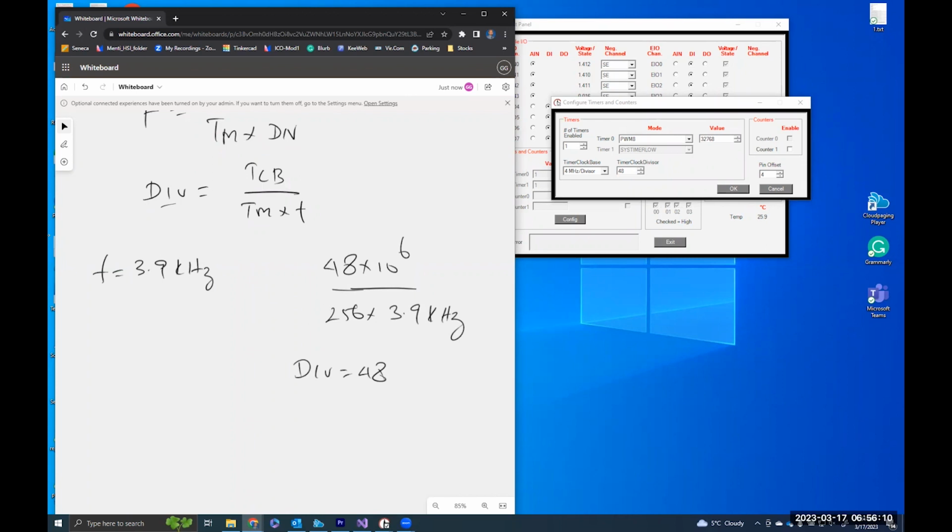Now, as I said, if your device needed 8 kilohertz and you need to set up this configuration, or the function generator here, to generate 8 kilohertz, how would you pick the number? So you set everything up here, the 4 megahertz, or maybe we can pick 12 megahertz per device, and we can choose, let's say, 16-bit PWM. So if you apply that, let's see how much we need to set the divisor with this setup to generate 8 kilohertz. So let's go for that.